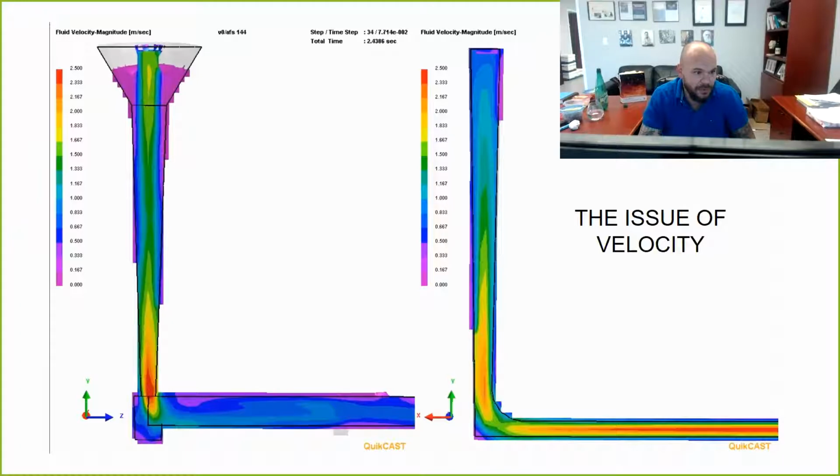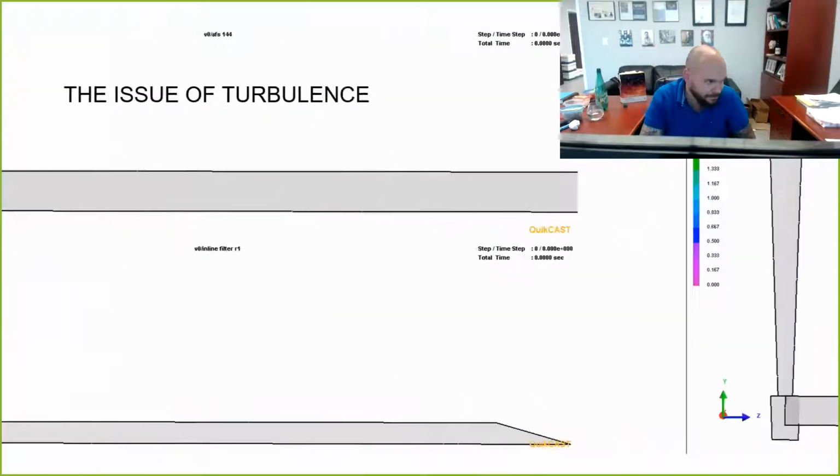What we'll see instantly, however, is that both of these are still running live if you look at the timestamp on the top right, although the one on the right looks like a photograph because it's in perfect equilibrium. You notice that the surface of the metal in the runner is not even moving, right? So basically, we've got no potential for the mold to get into the metal, air to get into the metal, gases to get into the metal, none of these kinds of things. And on the left, you can see that huge velocity fluctuation still taking place, which obviously means we have pressure fluctuation, which means we have pressurization and depressurization of the metal, hence depressurization of the mold cavity itself, which results in that aspiration mechanism and mold decomposition issue that we talked about.